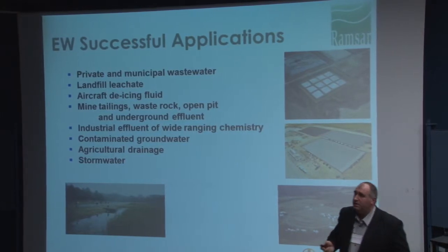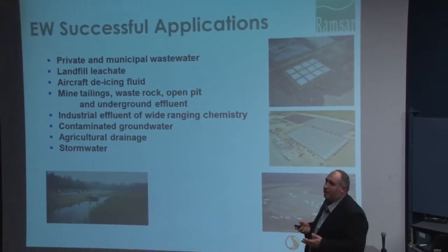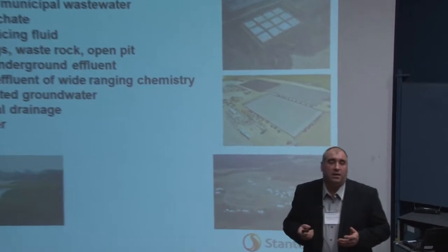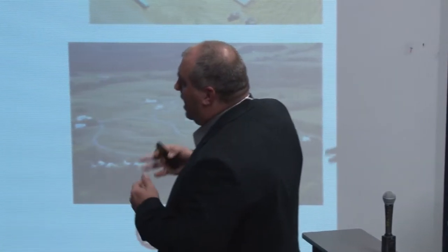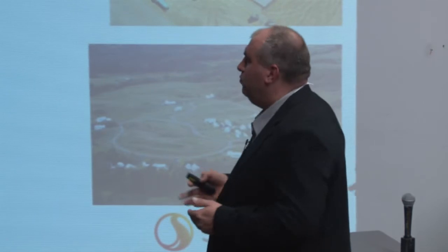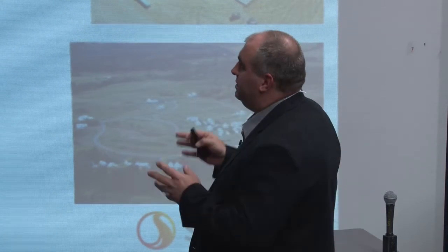For instance, the Cootes Paradise wetland has been treating the runoff, the discharge from the Dundas wastewater treatment plant since 1919, although it's a natural wetland. And those kinds of observations of the improvement in water quality that a wetland can achieve led to this growth in the field of using wetland science to deal with human wastewater problems.